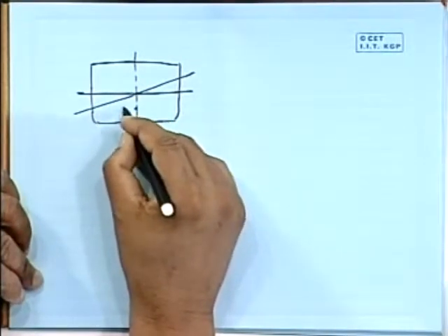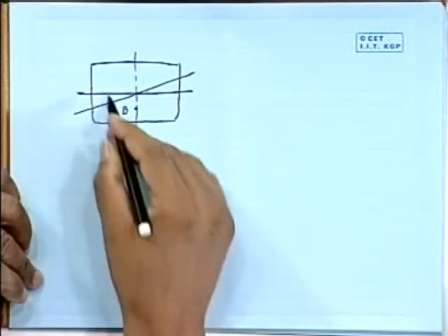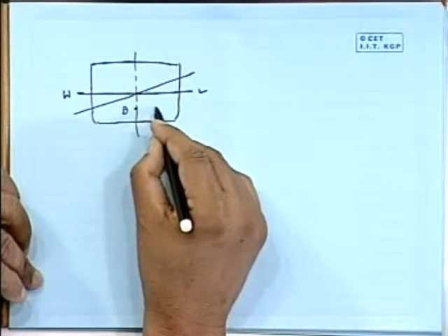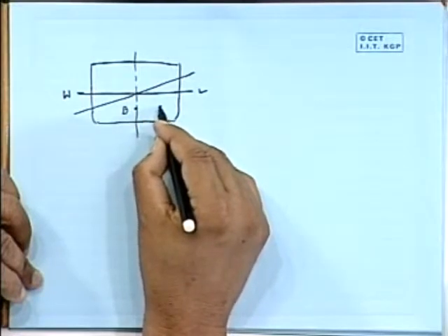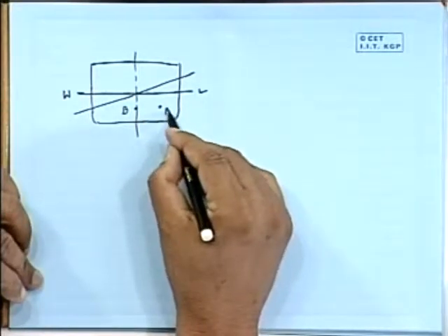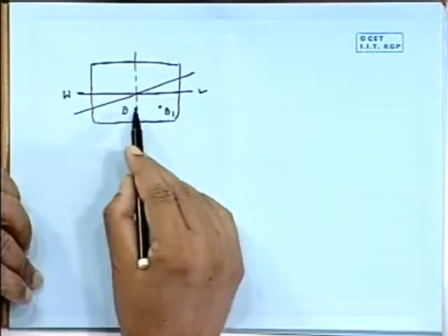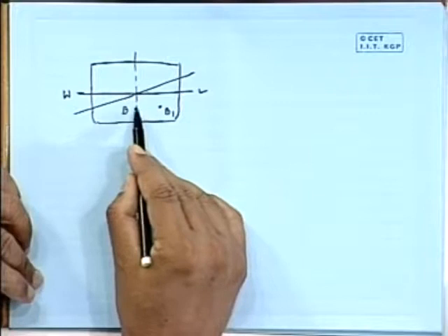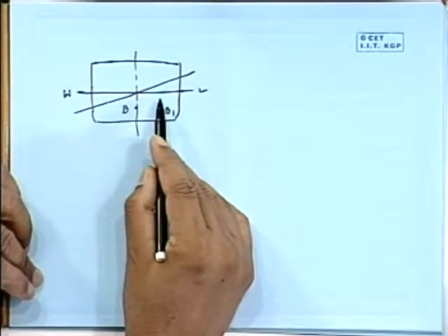This is the center of buoyancy initially, which is the center of buoyancy under the waterline WL. But this buoyancy center has basically shifted here to B1. Now again, is it shifted only horizontally? The question comes, or has it also shifted vertically?